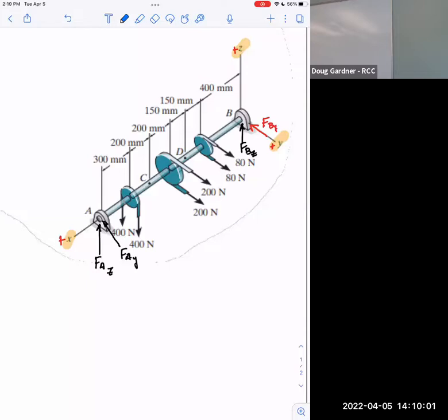And then those 200s, we just have to ignore those. Exactly, because they're not causing a tendency to rotate around the Y axis, because they're parallel to it. So whatever it's perpendicular to, that's the axis it's going to be spinning around. That's exactly right. It's got to be perpendicular to that axis. It's actually not new, but maybe it's painful.